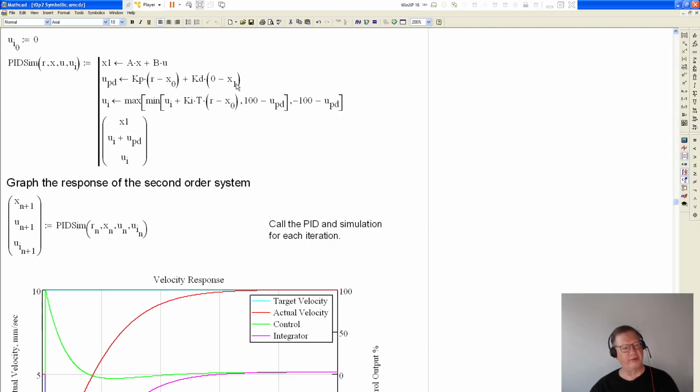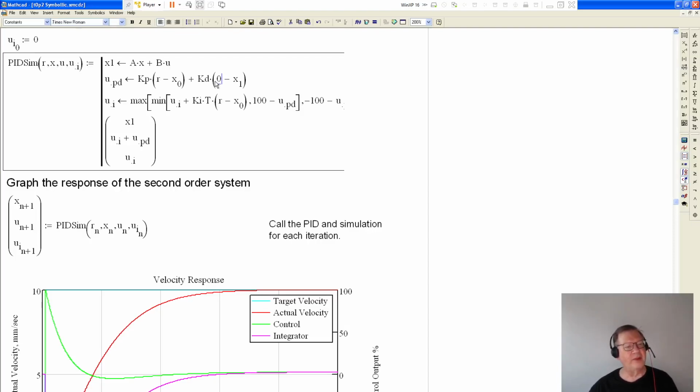This is the change in acceleration, excuse me. So what happens here is that we're not subjecting our system to that derivative kick by assuming that the target acceleration is 0. If I used positions to generate the acceleration, then you'd see that change in position, and that would cause the derivative kick that nobody likes.